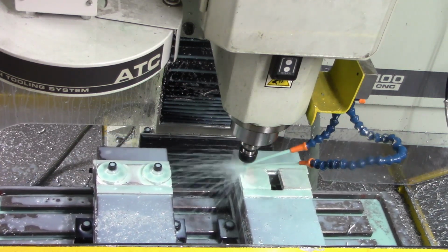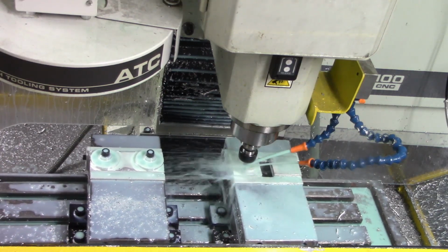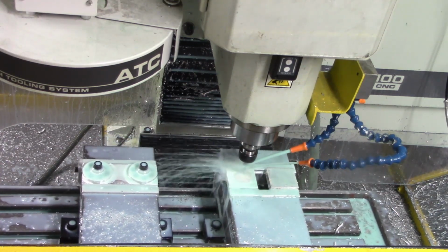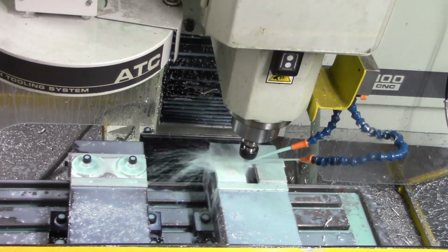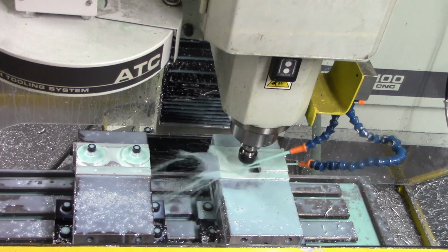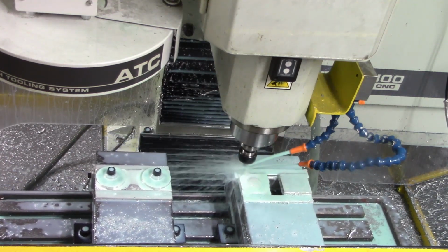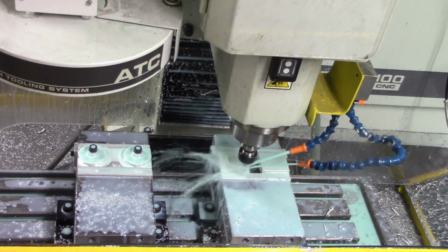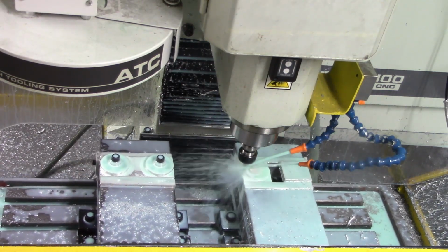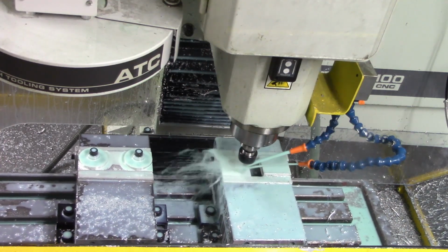passes. As I was optimizing, I thought, well, what if I slow down the feed and do it all in 1 pass? And so I tried programming a single pass at 30 inches per minute, and it chattered like crazy. No spindle problem, but the Tormach can't handle heavy cuts, or else it starts chattering.